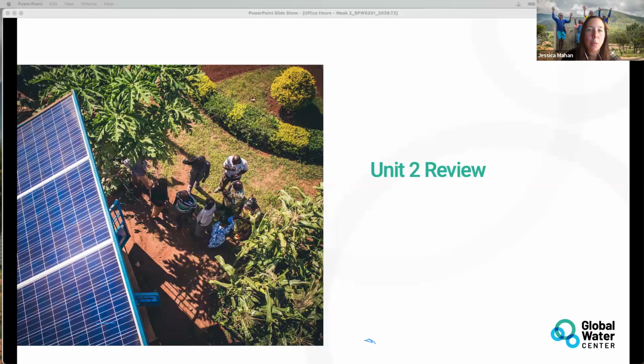In experience, one of the nice ways to do it is hopefully you have other boreholes in the area that might be within the same aquifer, and maybe those have had pump tests done on them, or at least maybe drilling records that have estimated the yield. Well, that's not as accurate as a true pump test. It can give us a starting point, right? Again, just to be able to estimate the pump that we need for that pump test. So those would be my two recommendations, either a drilling record that estimates the potential abstraction or records from nearby wells.